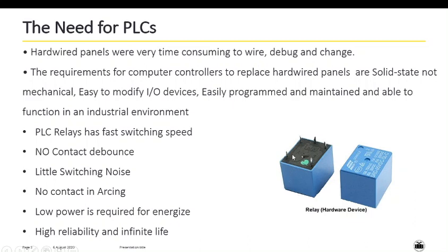But if a certain supply is connected to the primary winding, it will energize this internal mechanism, and there is a pointer in this NC contact which will disconnect from this connection and will be connected over here. So this becomes normally closed from normally open, and this will go offline. So it will be treated as normally open, not normally closed. Okay, so likewise we are going to do the connections.